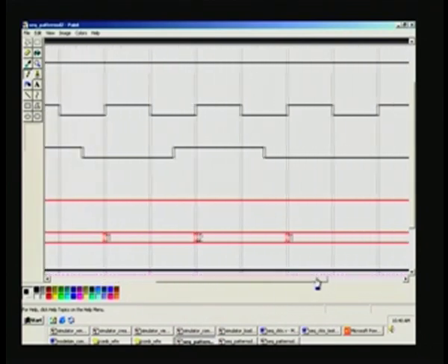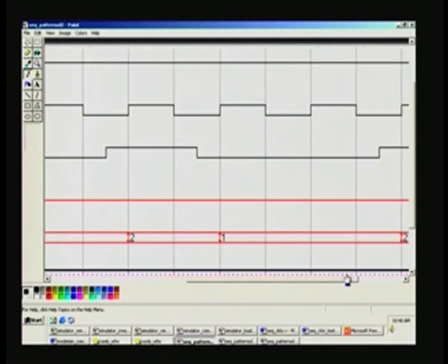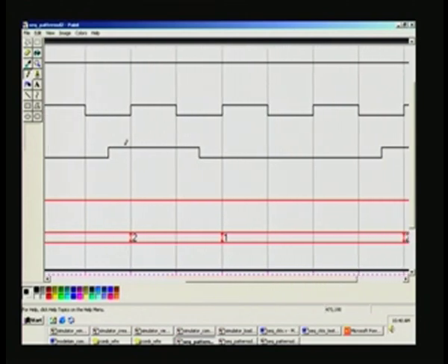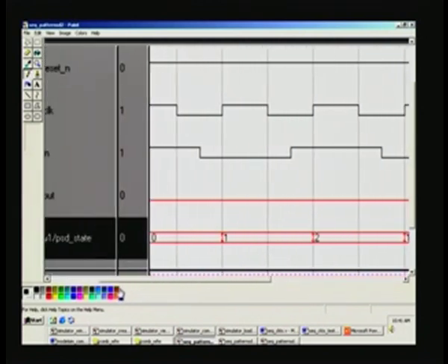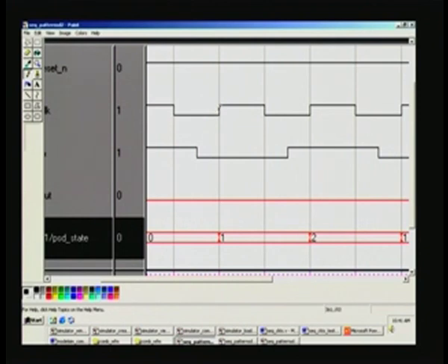So now at 2 let us put the same condition. At 2 naturally it is not this one, but this, yes. Go back to the first beginning. At the positive edge of the clock, the input is 0. So it goes to S1 state.